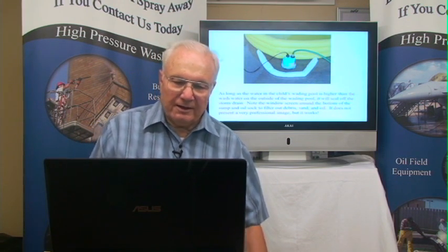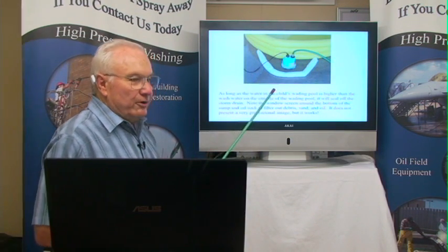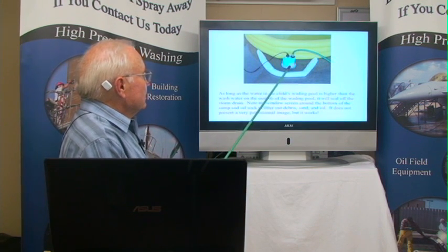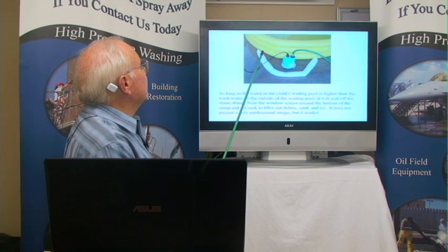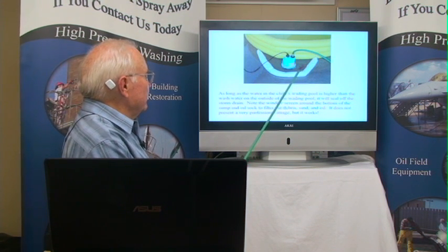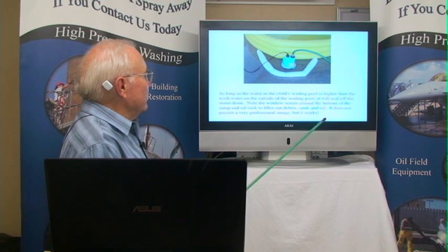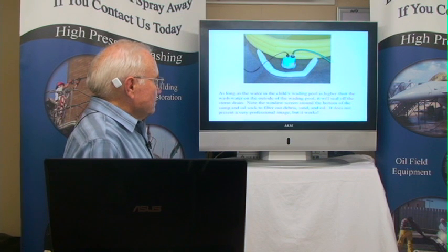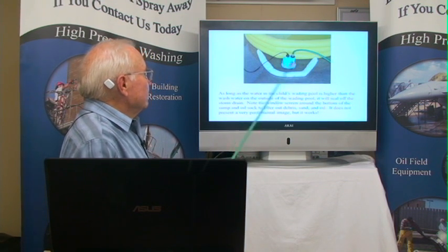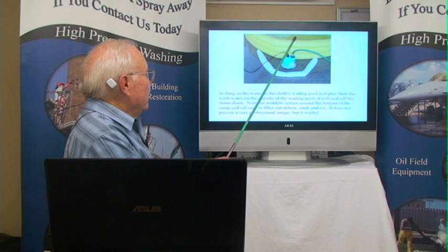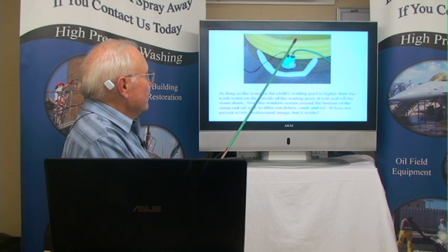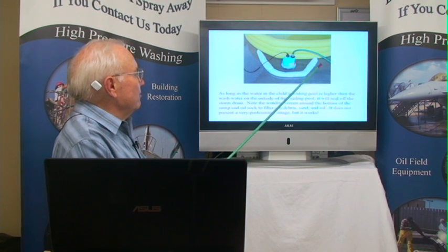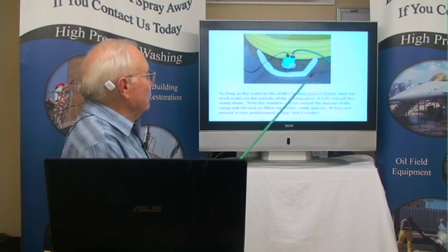Oh, here it is. Next slide up. I thought this was pretty unique. Contractor went out and bought a child's wading pool. He got a sump pump like from Home Depot. He put a whole absorbent boom around it and a screen down in the bottom. So he did his pre-cleaning with a leaf blower, and as long as the water is higher on the inside of this child's wading pool than it is on the outside, that'll seal off a storm drain real good. Doesn't look professional, but it works.